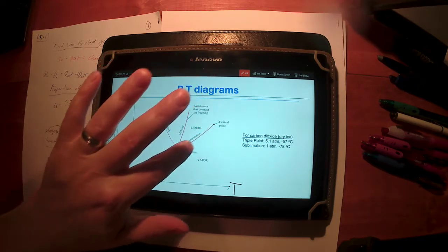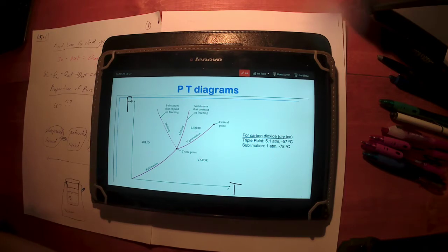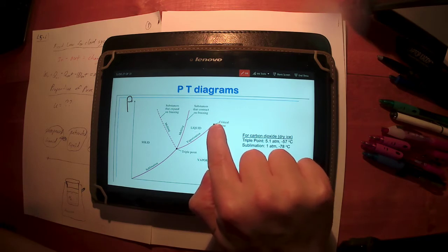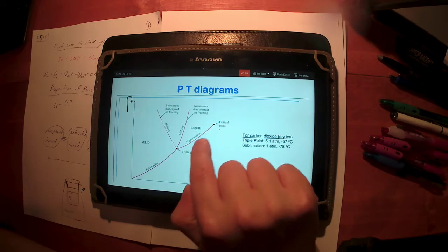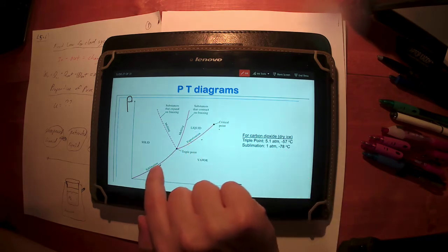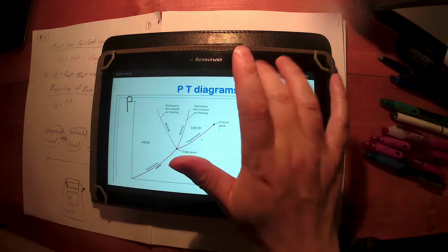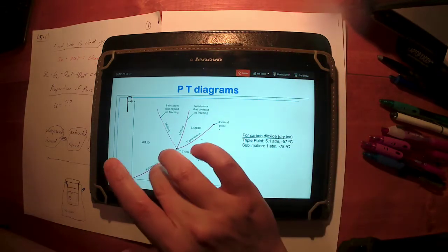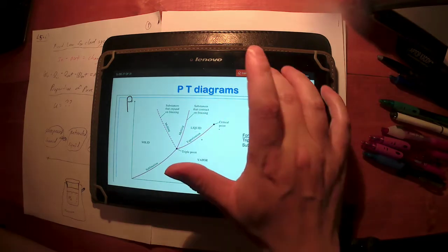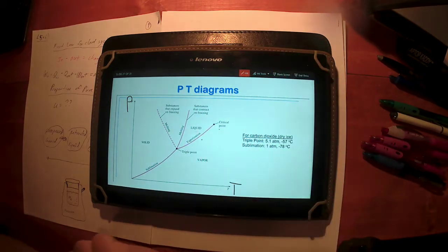When I just look at the edge of that dome, I just see a curve. Okay? And up here's our critical point, the top of the curve, and the bottom of the curve between the vaporization and what we call the sublimation curve is the triple point when viewed on this diagram. It's a triple line when viewed from the other diagrams.